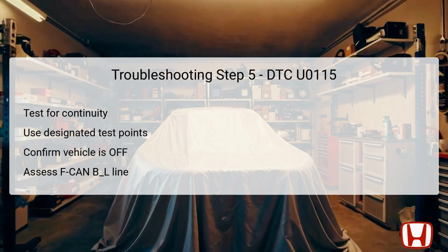Make sure the vehicle remains in the off mode and the PCM connector A is disconnected. Then, check continuity between pin 12 on the PCM connector A and pin 20 on the TCM connector. This check is vital for confirming that another essential communication pathway is functioning correctly.